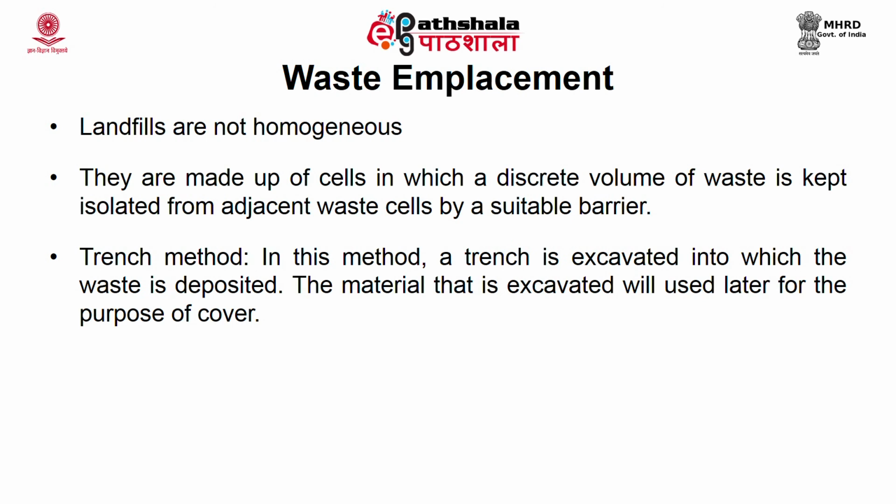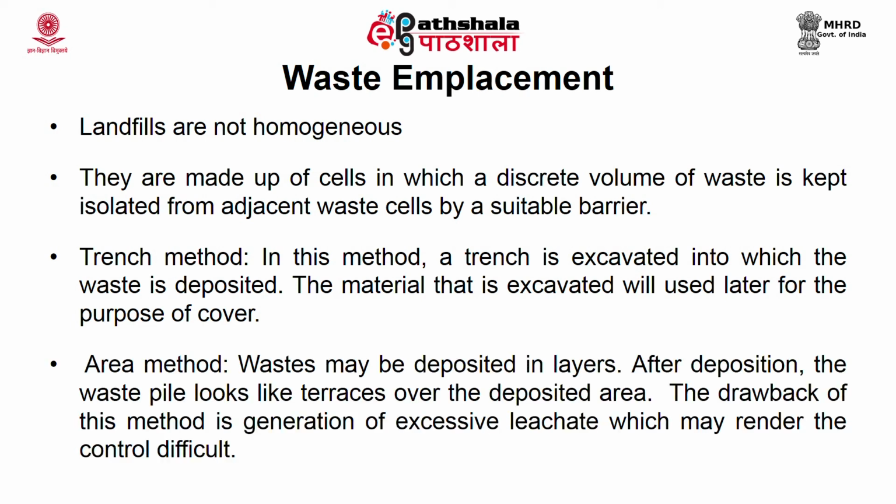In a trench method, the site where the landfill has to be constructed will be excavated, and once it is excavated, it forms a trench. Now, within the trench the waste will be deposited and the material which is excavated from the site is used as a covering layer. The next method is the area method.